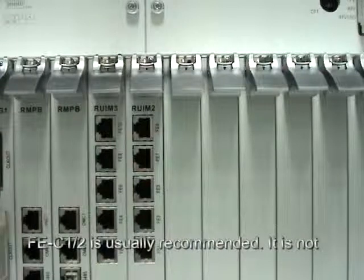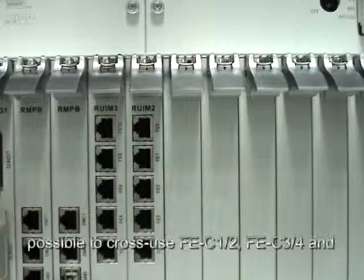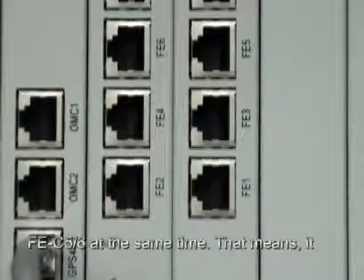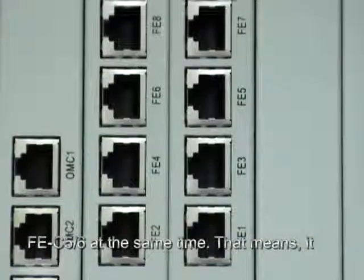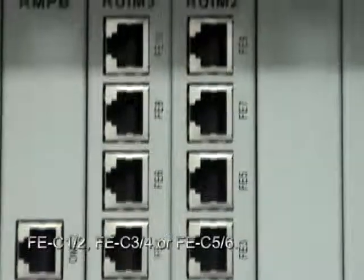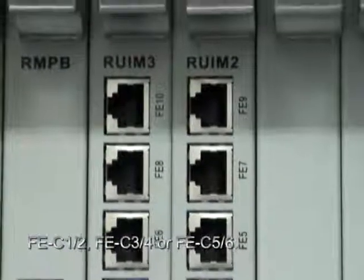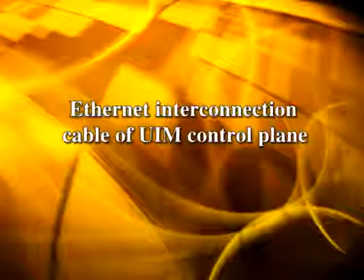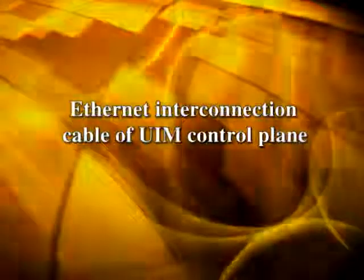FE-C1/2 is usually recommended. It is not possible to cross-use FE-C1/2, FE-C3/4 and FE-C5/6 at the same time. That means it can only be configured at either FE-C1/2, FE-C3/4 or FE-C5/6. Ethernet interconnection cable of UIM control plane.